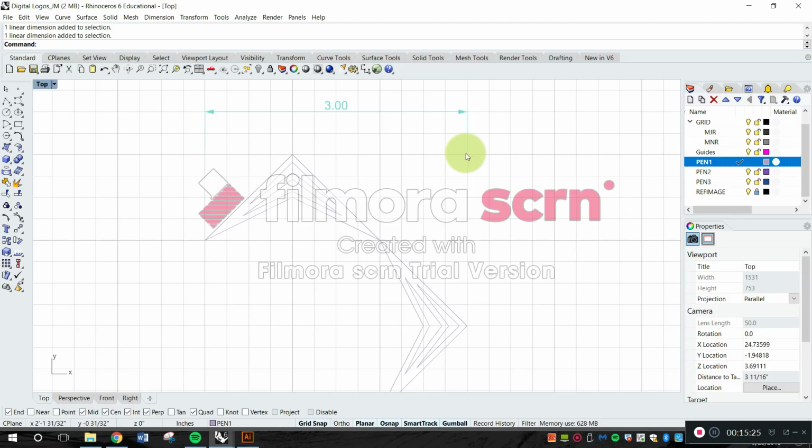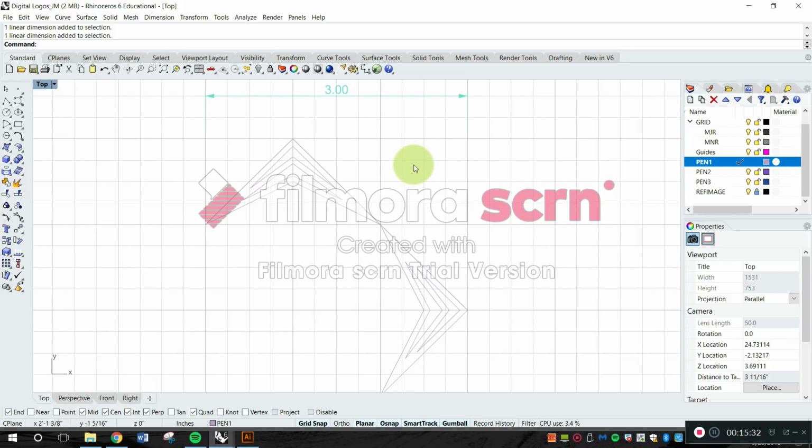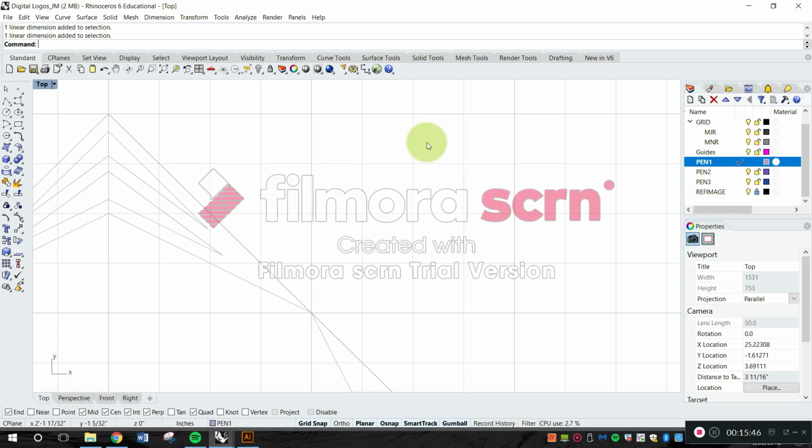Now, this already tells us a little bit about how Rhino is dividing its grid, and this already sort of highlights how we're going to be using the minor and the major grid. These are major grids right here, and we can see that the major grid is made up of 4 segments, so it's divided in quarters: 25, half, 75, and a full one.